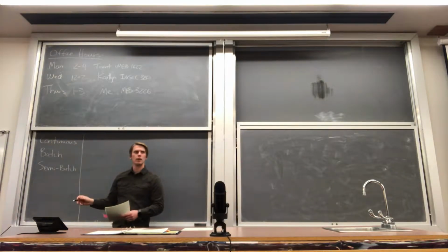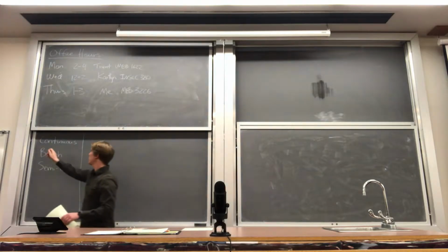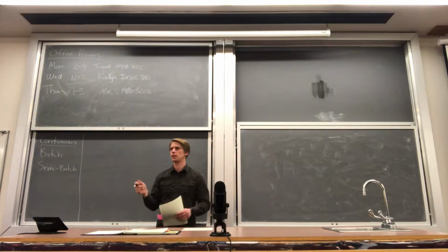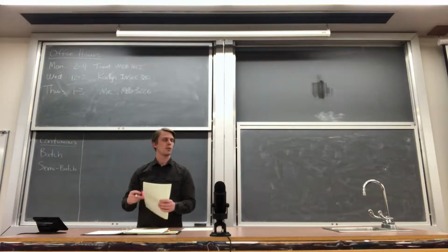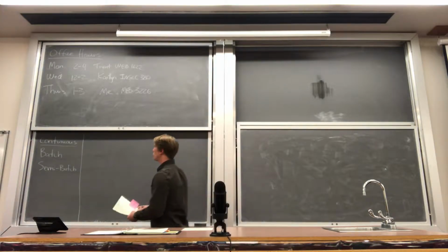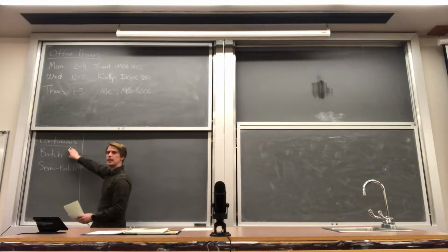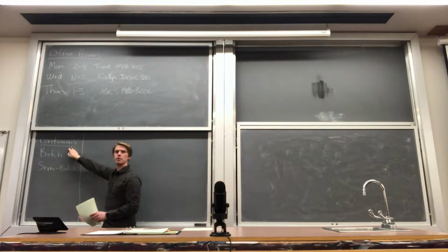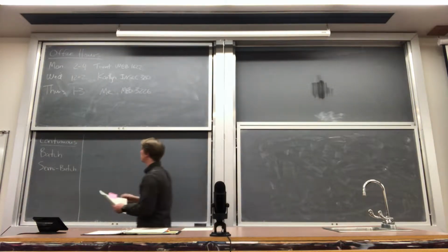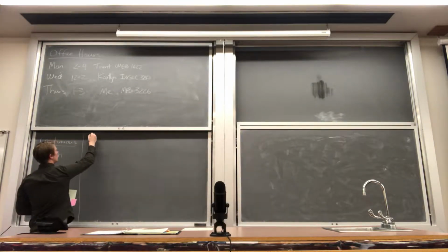Now in general, almost everything we're going to be talking about falls into a continuous process, because that is the way that we can optimize the efficiency of it, and it's the easiest one to perform calculations on. So in general, we are going to be assuming continuous and steady state. Those are general assumptions, which basically mean that nothing is changing as a function of time. And to talk about that, I'm going to introduce now the general balance equation.